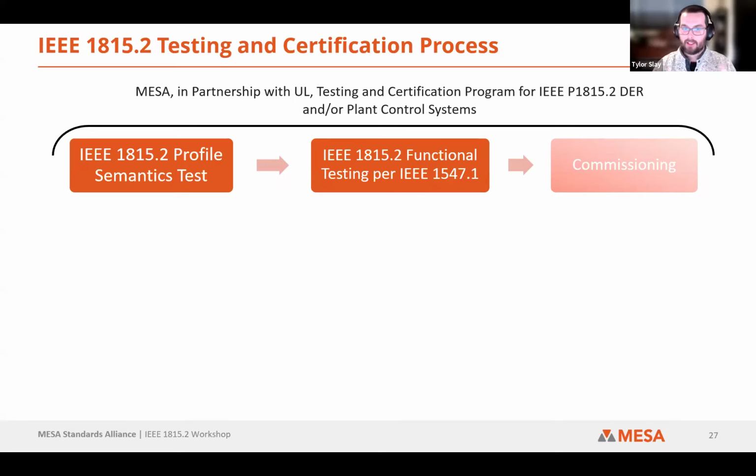Is it, as we outlined with the scheduling, multiplexing those schedules correctly when it gets a switch command to go to a different schedule index? And is it enforcing the maximum upper and lower bounds of the point in particular? And is it scaling that point correctly? So that's all included in the semantic tests.